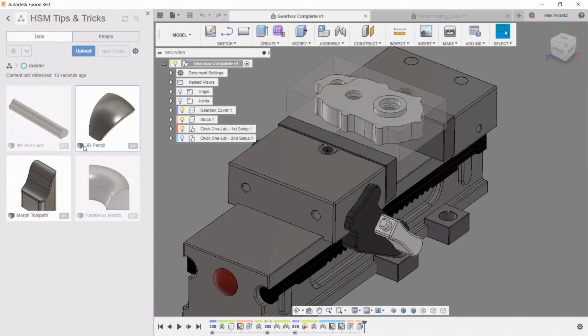You can work in offline mode, but keep in mind if you are going to be traveling and you haven't opened this model in quite some time, that you add it to the offline cache. If you are working with these models day in, day out, they're automatically going to be added to the offline cache. So there's nothing on your part that you need to do. It's automatically going to add these files to the offline cache.